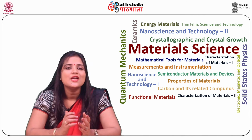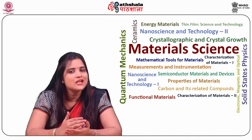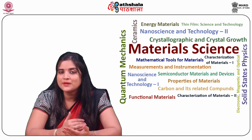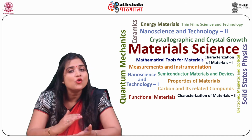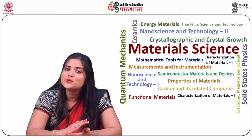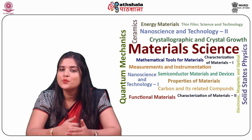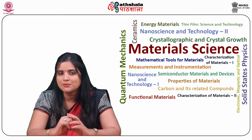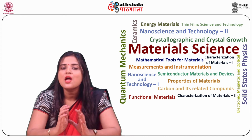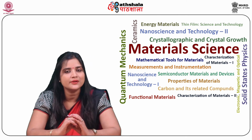Negative feedback is used in amplifiers as it stabilizes the gain, increases the bandwidth, increases the input impedance, and decreases the output resistance. Negative feedback also reduces the variation in output of an op-amp due to variations in temperature and supply voltages. Thus, we will be studying op-amp in negative feedback configuration over here.